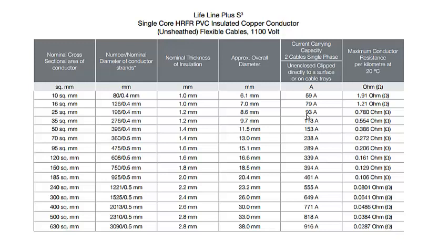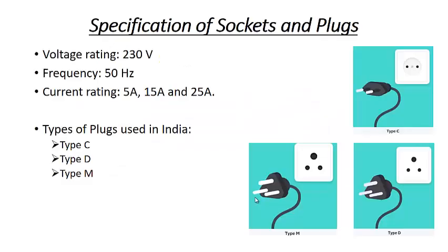They might have this much load, that's why they have to install 25 square mm as the main conductor or main wire. So you can use this data to design different types of wires, and as per this you can install these wires.